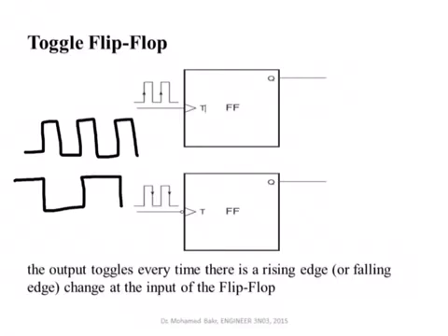So you see your output frequency here is 1/2 the input frequency. So this circuit effectively divides the frequency of your square wave by 2. And if you cascade another one, then we are dividing by 4. Another one, we divide by 8. And this is why these toggle flip-flops are very useful in creating binary counters.